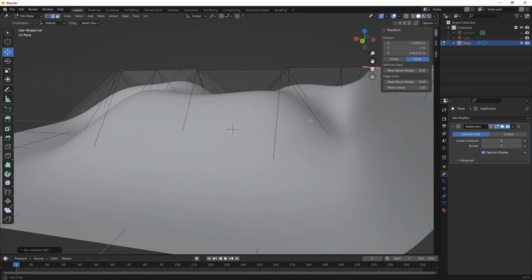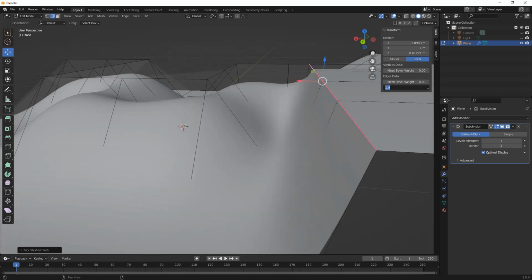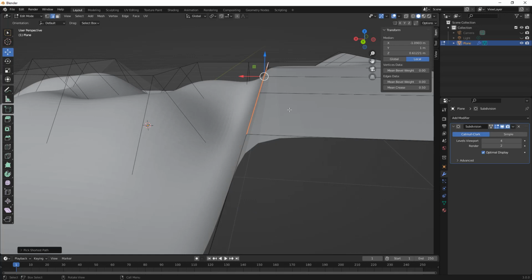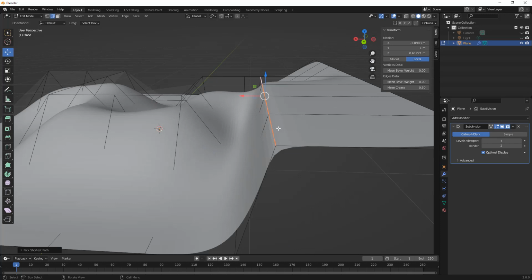And you can see here that we've created this tight corner or this tight edge. If I change this to 0.5, what we've now done is we've added a half weight, somewhere in between that completely smooth and that complete crease. So this is another way in which we can control the edge flow.